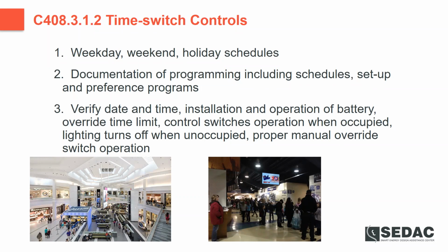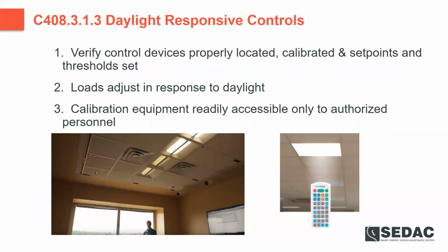I've been in a building that had time switch controls installed that were actually wired up backwards, where an off command turned the lights on and an on command turned the lights off. So again, commissioning, very important to make sure that those things are working properly.